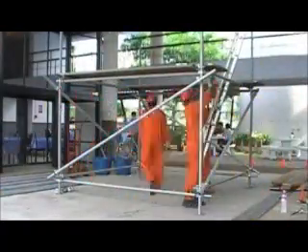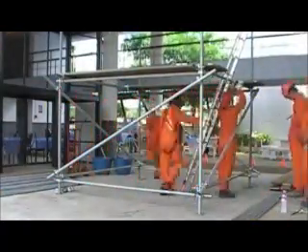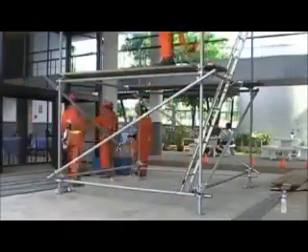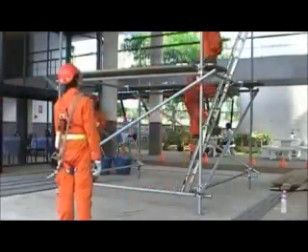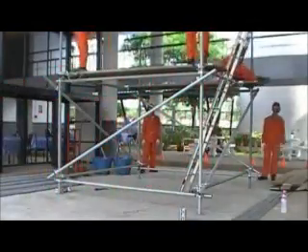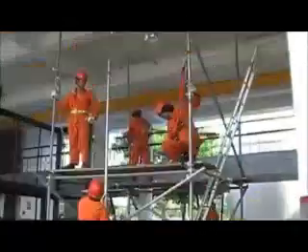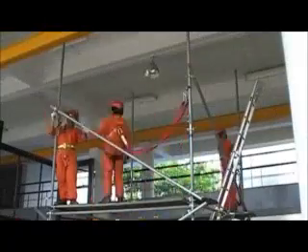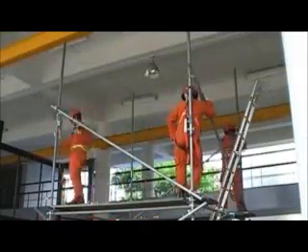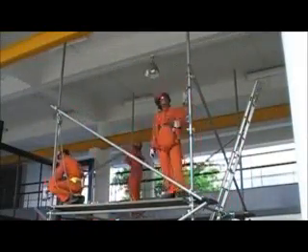Independent scaffold can be done by cup and cone arrangement. To extend the post, joint pin can also be used. Maximum height of structure can be taken up to 38.1 meter. Necessary bracings are to be ensured: cross bracing, transverse or longitudinal bracing. For overhanging, knee bracing is also to be done.